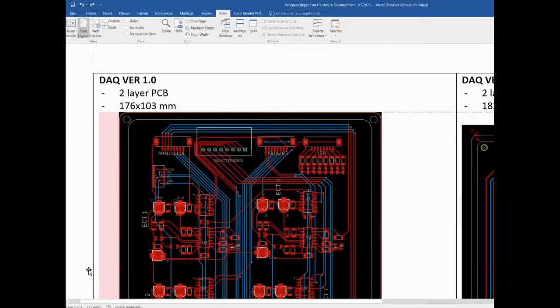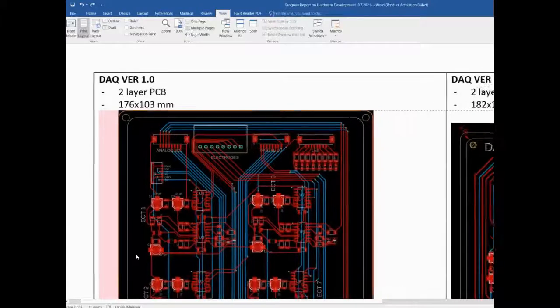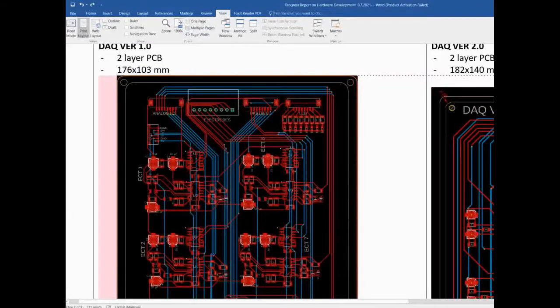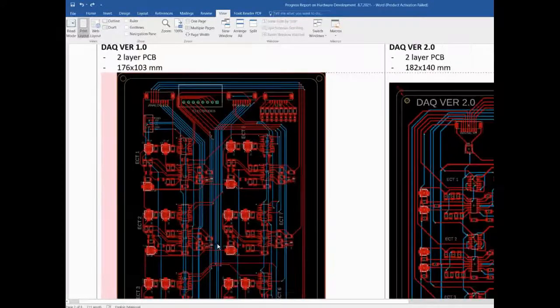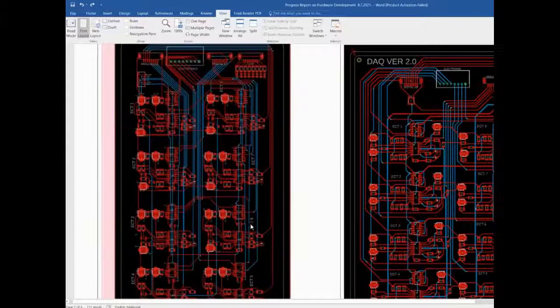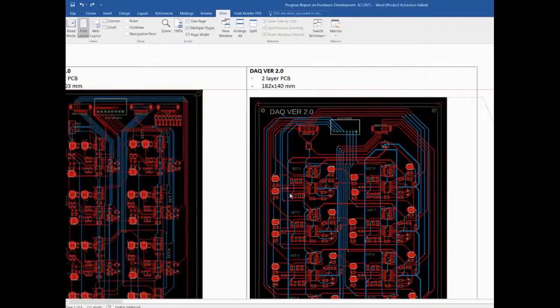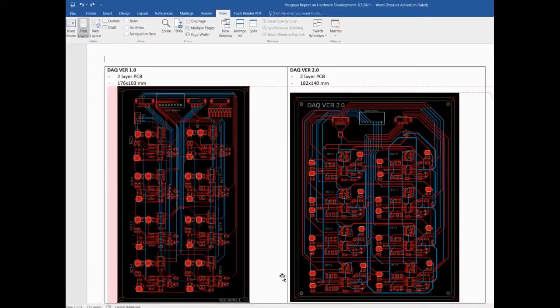And also in the first design, in this version, I mixed the power supply connectors with the sine wave, with the ground, with the power supply for the switching IC, because there are two different power supplies. This is 5 volts and this is plus and minus 9 volts. So this whole thing causes EMI problems. And also the spaces between the traces are narrow, so this causes crosstalk between signals carried in the traces.